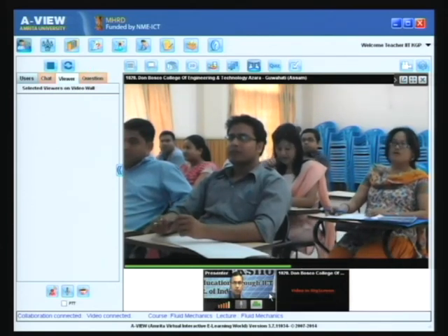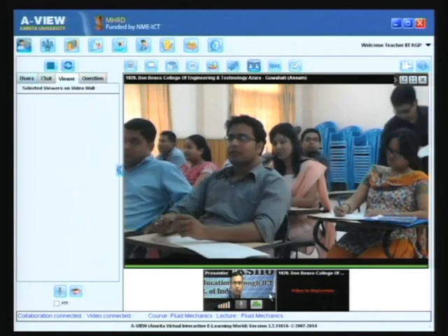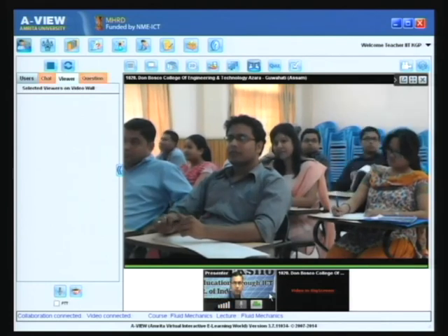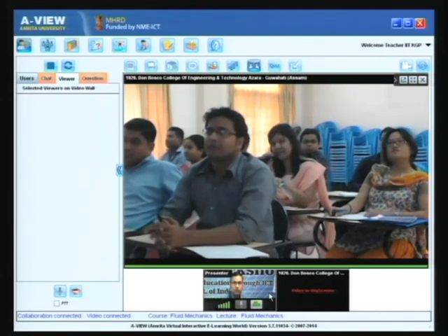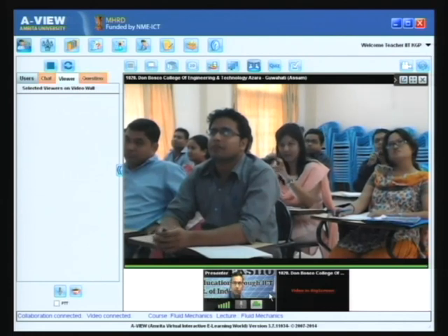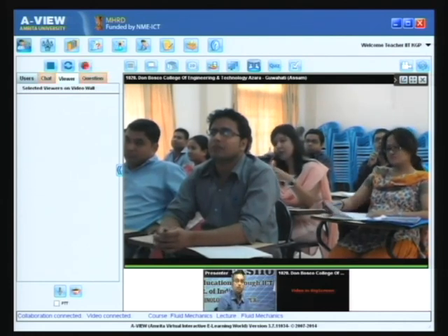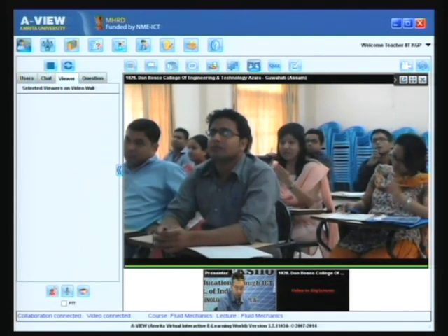My question is about the relation of Knudsen number with free molecule flow, slip flow, and transition flow. Actually, I want to know how you determine the characteristic length when we speak of Knudsen number. Like mean free path, we know it is the distance between two collisions. So I want to know how we fix the characteristic length while defining the Knudsen number.